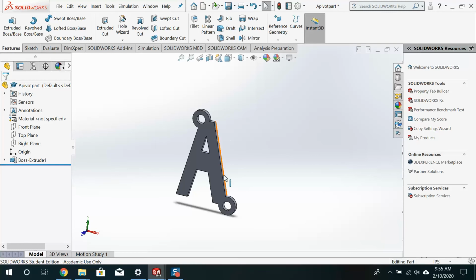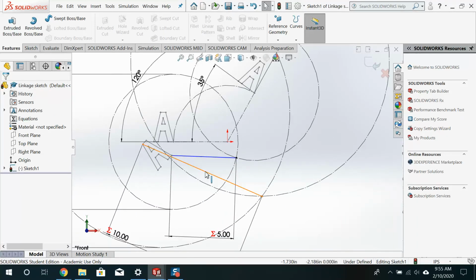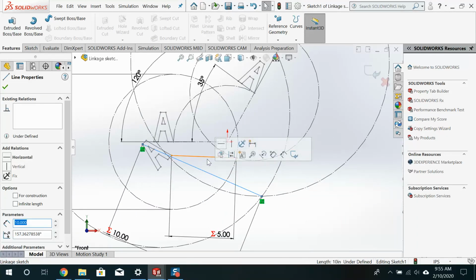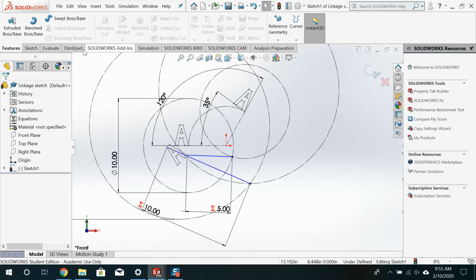And so this is the thing that I'm going to end up pivoting. Now I need 3 more bars, and the reason why I need 3 more bars is because if I go back to my linkages, I need 2 bars for the linkage, one which I'm calling a long bar here, another which I'm calling a short bar there, but I also need a bar that connects the 2 base points of this linkage. Because if I don't, then these twos aren't going to be fixed, and they're just going to float everywhere and freely spiral out of control. So I need to understand that as well.